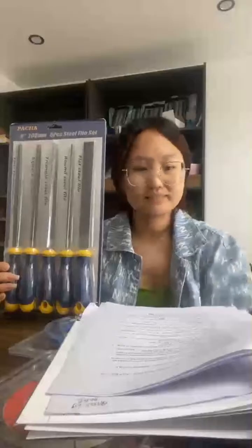The right way is to use a wire brush to clean the cuts according to the direction carefully. Third is don't use it too fast and make sure the file is used under stable conditions. If the file falls from a high position, it will break and be dangerous. These are the points to note when using files.